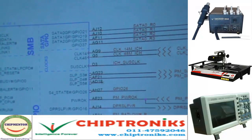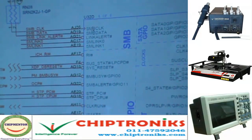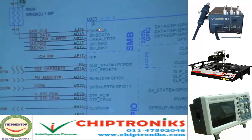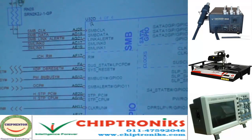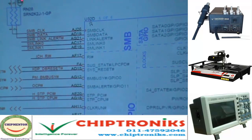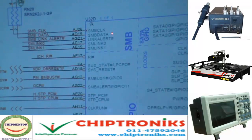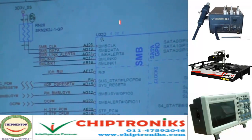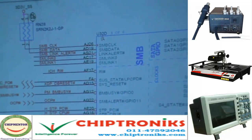Page number 20, this is very important. This is the system management bus controller section of the ICH 8. If it doesn't get 3.3 volt S5, which means after pressing the power button it will get 3.3 volt, then the connection between the ICH and the CPU won't happen.